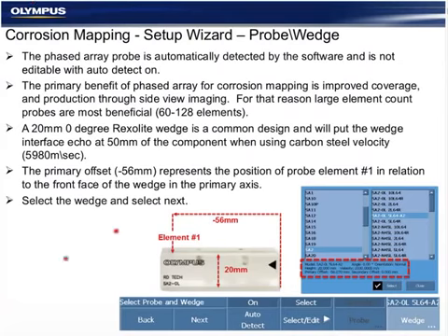The software needs to know a lot about the wedge to be able to form the beams correctly. Wedges account for the overwhelming amount of our support issues due to the phased array not performing like the customer intends. It's not automatically detected by the software, obviously, so it must be selected from the database.